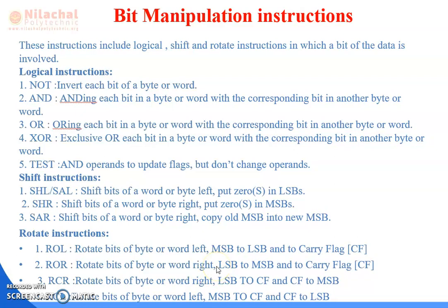Next one is shift instruction. So SHL or SAL, that means shift bits of a word or byte left, put 0 in LSB. Next SHR, shift bits of a word or byte right, put 0 in MSB. Next SAR, shift bits of a word or byte right, copy old MSB into new MSB.